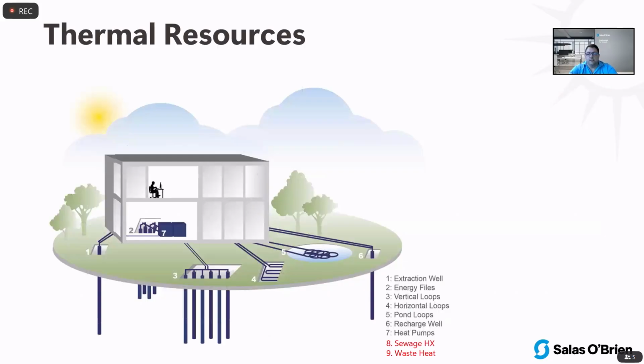Thermal assets or thermal resources, Nick did a really good job talking about this. Obviously we've got all kinds of different earth energy type systems where you're talking about vertical closed loop, surface water, open loop reinjection, energy piles. There's all kinds of really good geothermal resources, but there's also that waste heat that's around all of our communities that we can try to take advantage of. And so those are the thermal assets that we've always tried to analyze and figure out: is it available? Is it accessible? And then what's the cost implication of that thermal asset?